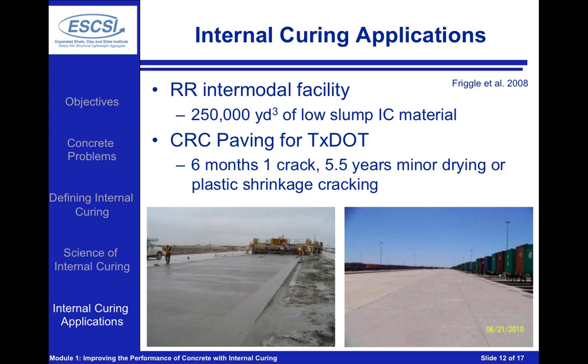Other internal curing applications: here we can see an intermodal railroad facility where substantial amounts of low slump internally cured concretes were placed. Internal curing has the potential to reduce curling and reduce cracking, and these can really extend the life of pavements. We can also see some pictures here where internal curing was used in some continuously reinforced concrete pavements with TxDOT, where they had the ability to reduce cracking and also to reduce the potential for plastic shrinkage cracking when these pavements were being placed in a high evaporation environment.